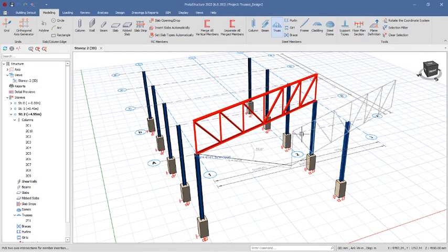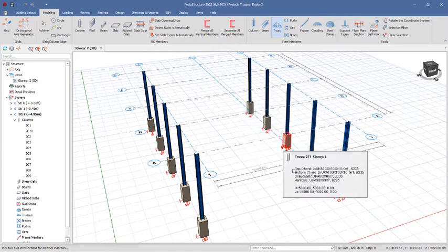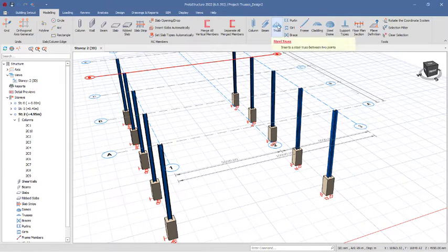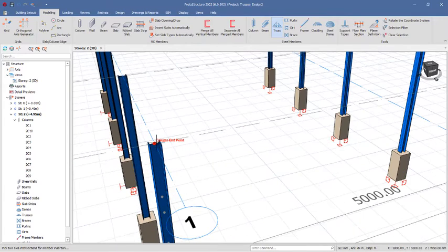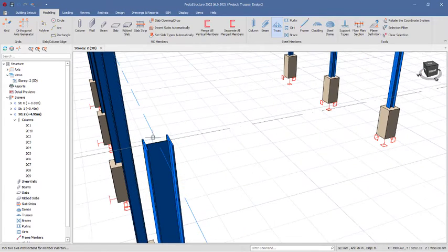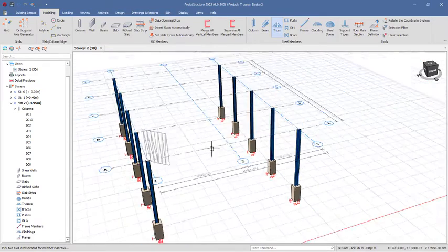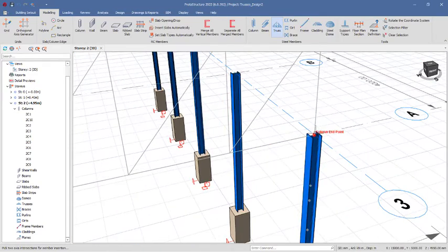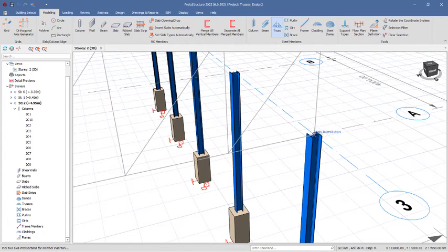Let's click on OK. You see, we have not actually placed it right. So you have to delete this. Pick the truss options again. Pick this first point. Make sure you always zoom closely to be able to get the right node point, because if you pick wrongly, you may not necessarily get what you wanted. So ensure you always zoom closely, click right there.